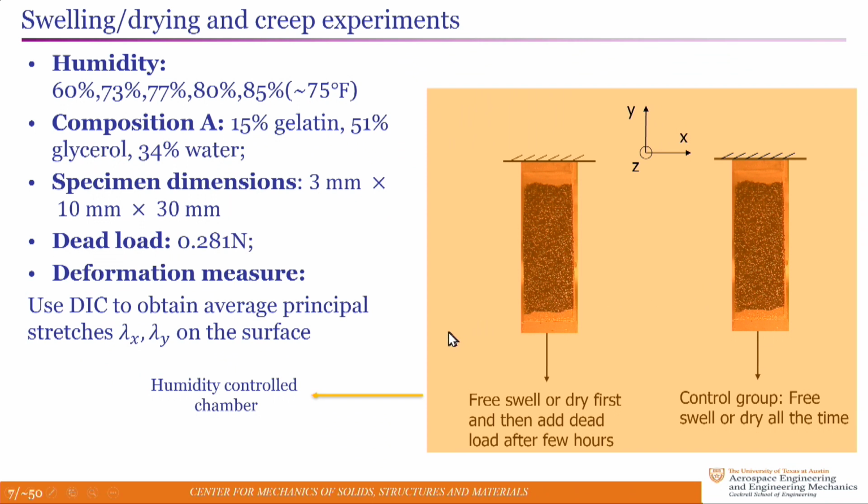The rest are details, but we do decorate the top surface of the specimen with a collection of titanium dioxide powders on micron scale particles, and we're able to image that with a camera, keep taking pictures every 10 minutes or something like that over a time frame of about a week in order to see the entire diffusion process as well as the creep process.